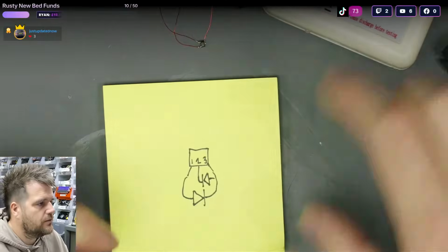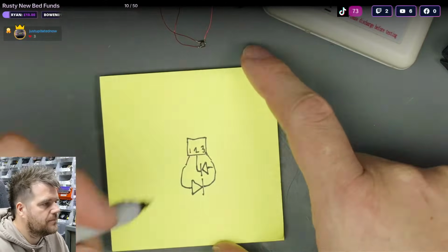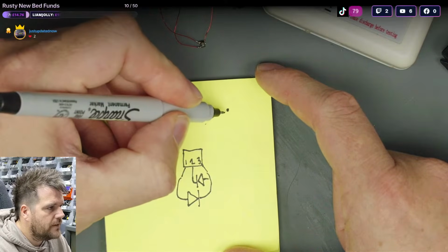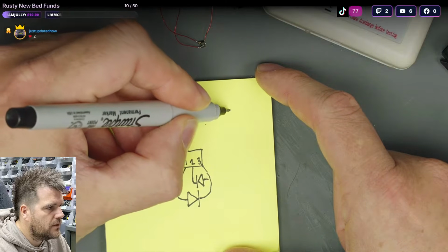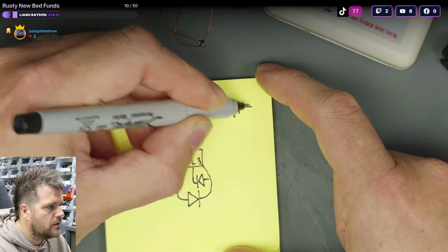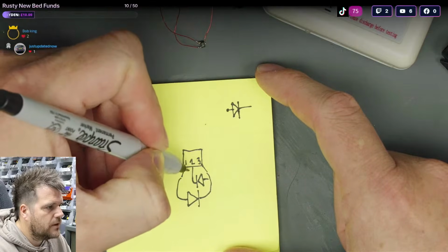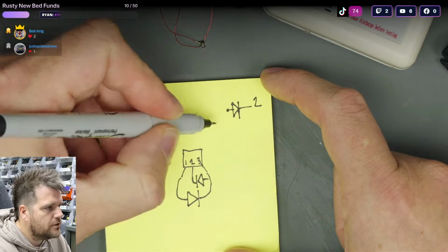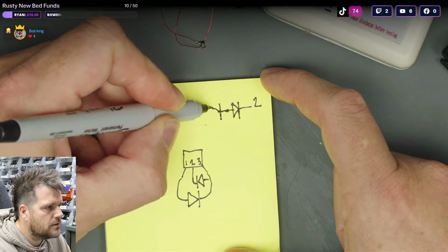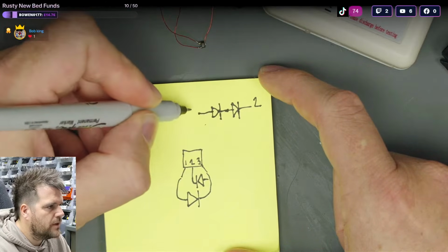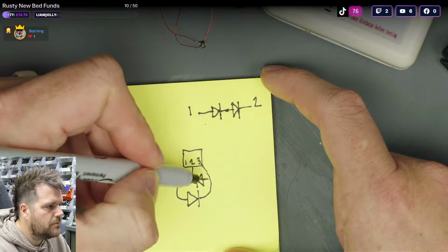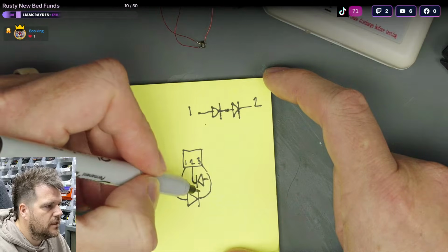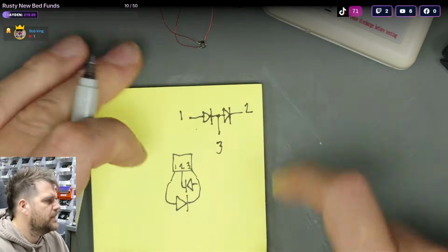So if that's right, we've got something like this in a package, which means, drawn a little bit easier, they've got an inverted pin like this. So we would have, typically, this would say go out here, over to there, and that would be this diode going over to there, which is pin 2 over here. Then you've got the common point here going back to another flat, so that would be a flat like this, going over to pin 1, so that's pin 1, pin 2 over there, and this shared pin is pin 3. So that's basically how you draw it in a schematic.